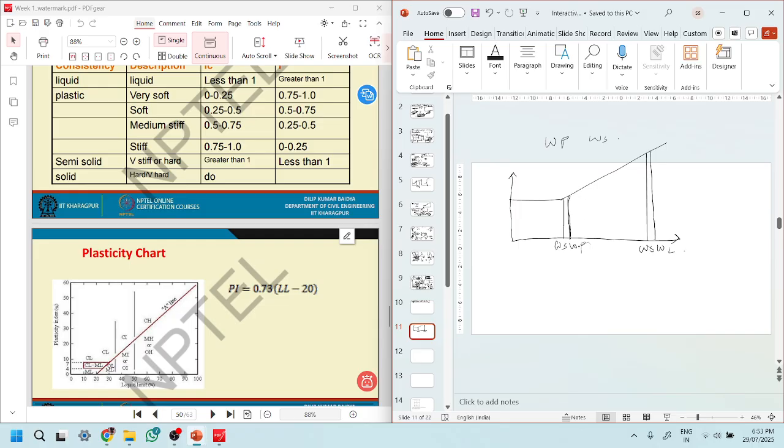And why I am saying that is because, first of all, if we talk about plastic limit and liquid limit, it is not possible for a slurry to be like, see, in this case, what is happening is that the soil does not have plasticity at all. Narrow gap. Clay content is less.